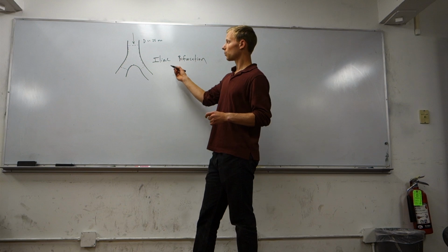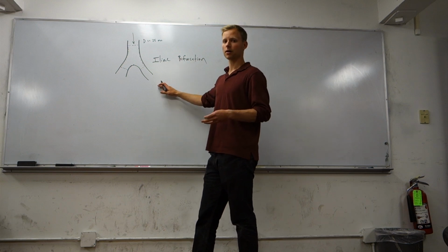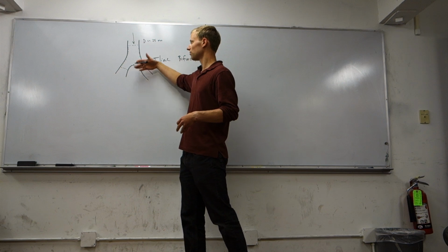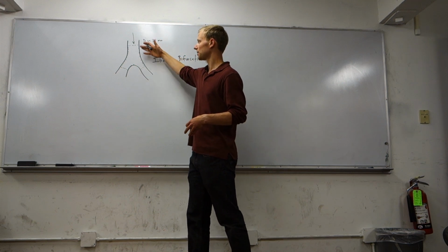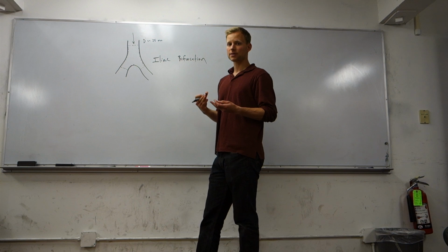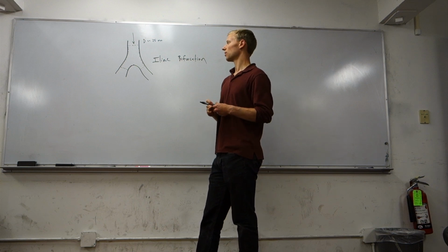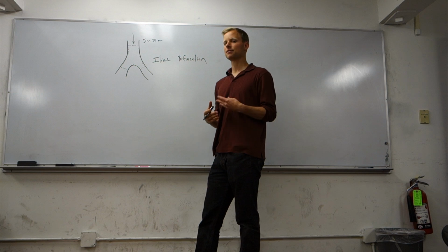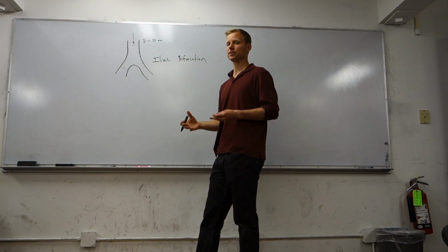Particle image velocimetry would work in a laboratory setting where you could build your own geometry and maybe provide a controlled environment where you see particles upstream and then visualize where they go. That might not be the best option for doing something that's more real world with different geometries. It could be a time-intensive, expensive experimentation to give a bunch of geometries.